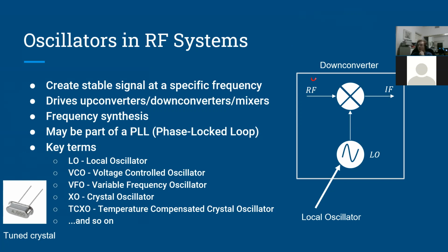If I say this one is omega 1 in frequency and this one is omega 2, what you said is correct, but there's a little more to it. The output would be something like cosine of omega 1 t times cosine of omega 2 t, assuming they're in phase. They don't necessarily have to be in phase. This would be a simple case of amplitude modulation, like he said.